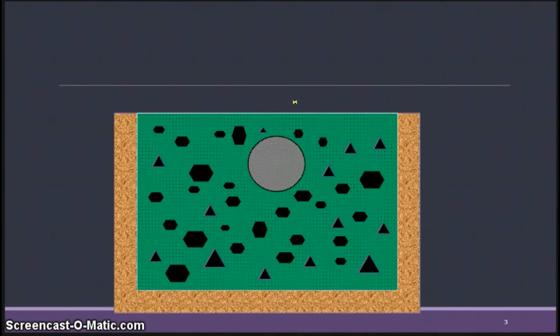Now, whenever the concrete undergoes volume changes, it's going to subside because it does not have any chance of movement in these directions wherein the formwork is present, provided that the formwork is very hard and stiff. Obviously it does not have any chance to go down either. So the volume change occurs because of the subsidence.